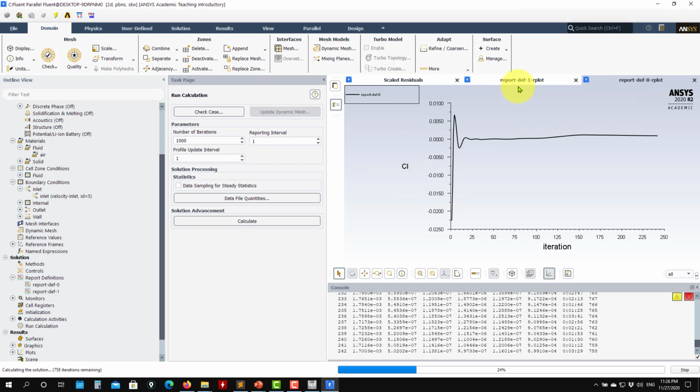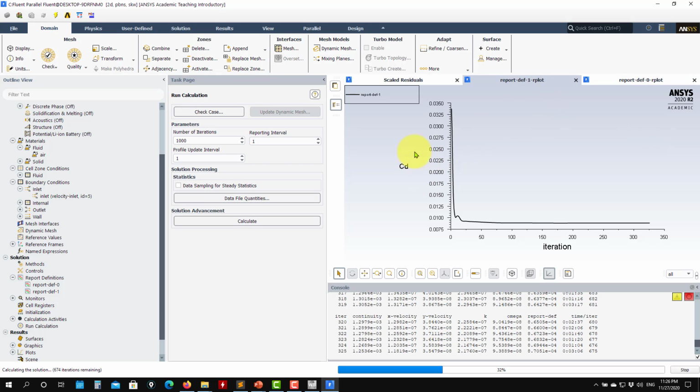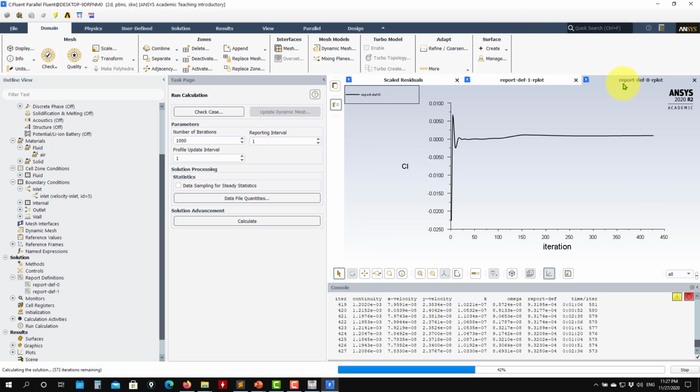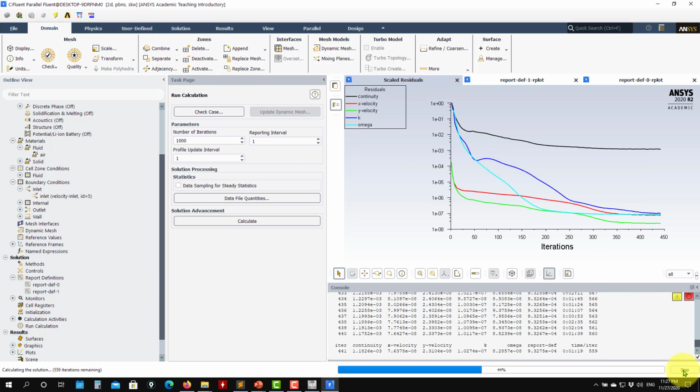And see here that you have CL and CD, and see that it's not oscillating. This is a good indication. This means that probably you have arrived at a converged solution. See that CL, as expected, should be about 0. See here that it's getting to that value. Then you have CD0, this one. So here now you have everything, all the viscous effects. As you go to 3D, you are also going to have your skin friction plus induced drag, everything. And if you want to do the decomposition, it's a little bit trickier, but you are getting here the actual forces, everything.